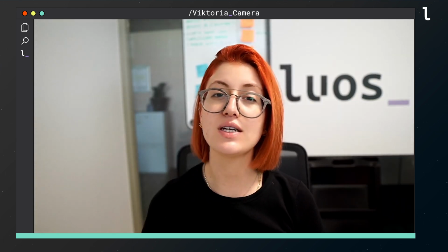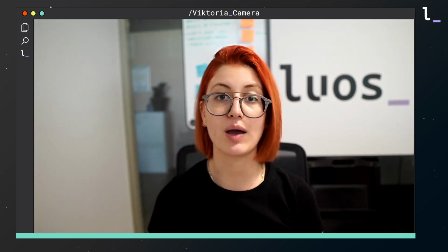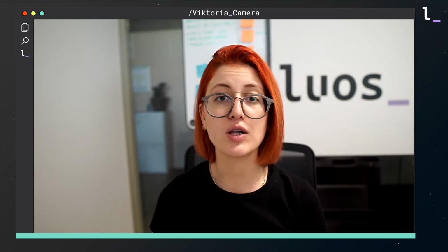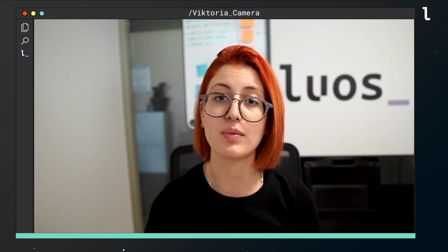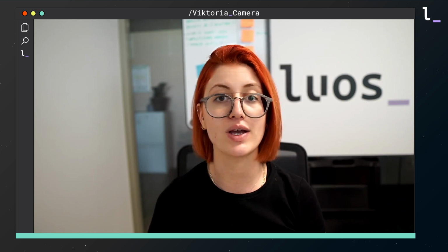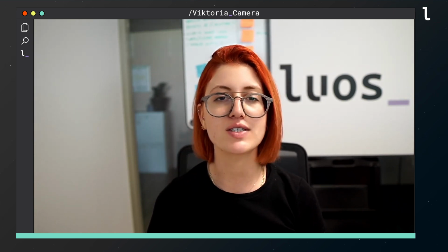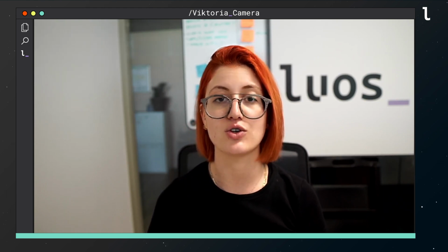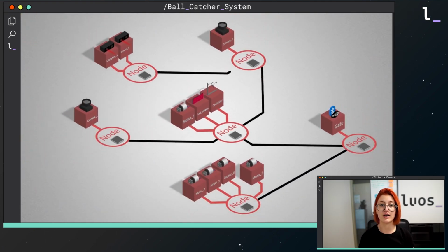Up till now we have seen that we can control the solenoid and the sensor using Python and the Luos Python library called PyLuos. However, I decided to transfer the functional part of this project into an embedded application so that I can use the timestamping tool and transform my system to a real-time one. This application will be a Luos service like the drivers that I have already created, and I will put it in the same Arduino board with my sensors. The application will communicate with any other component of my network using the Luos communication protocol.